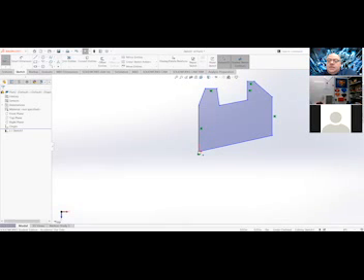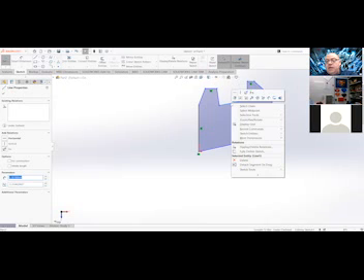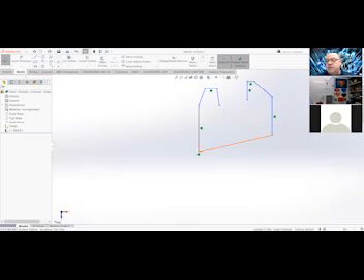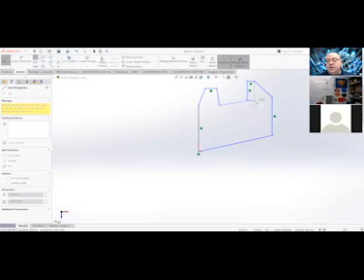Okay. Now, to delete a line is just like in AutoCAD. If you make a mistake, take your cursor without a command being active, select the line. You can right click and hit delete, or you can hit the delete key on your keyboard. Now as soon as that line goes, notice it's not a potential 3D model anymore. I have to come back and draw the line back in.